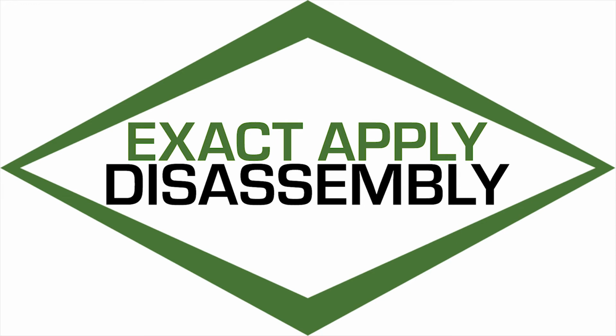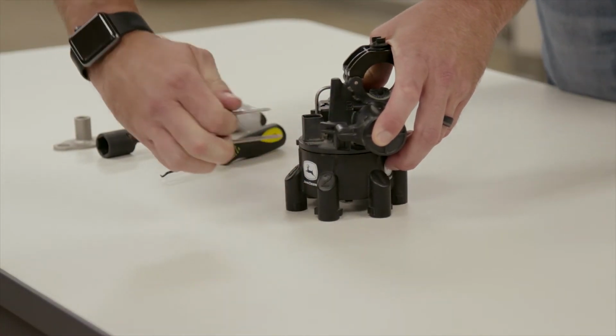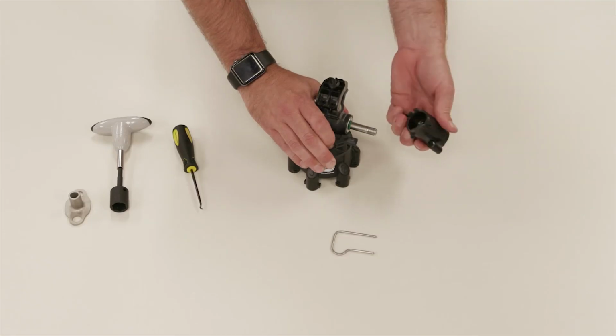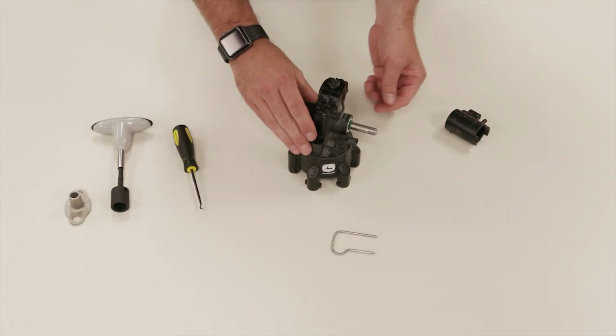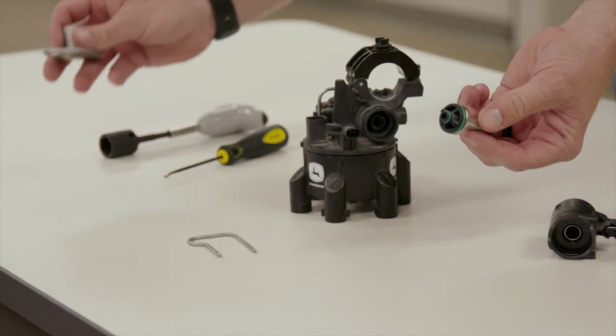In this video, we're going to look at breaking down our ExactApply nozzle body, whether we need to service it or you have a nozzle dripping. This video will walk through breaking down the different components. First, we remove our retaining clip. After that, we remove our coil pack. That's where the actual PWM magnetization happens. From there, we remove our valve stem. Notice the O-rings and the black cap.